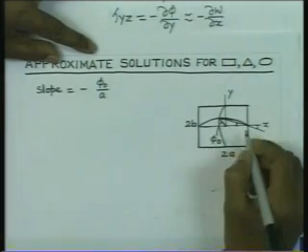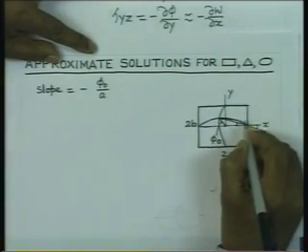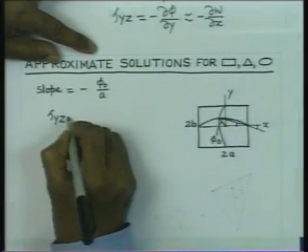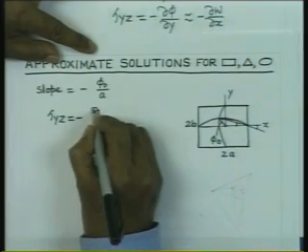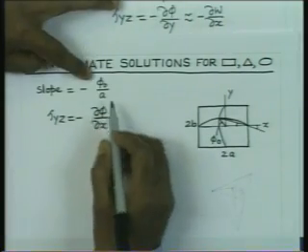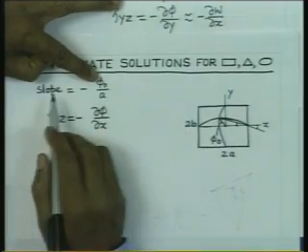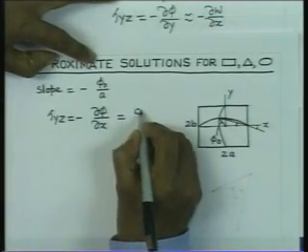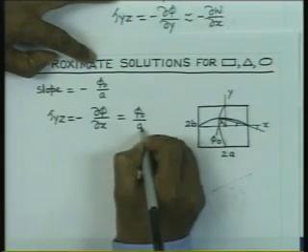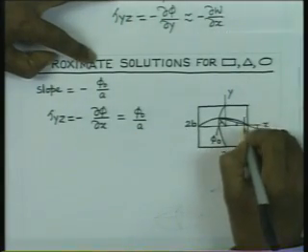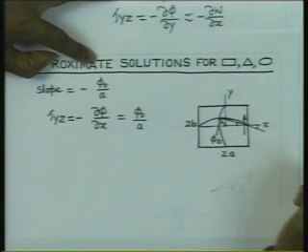And now we know that the shear stress which is going to act parallel to the boundary, which is nothing but tau yz, is equal to minus delta phi delta x, and we get that delta phi delta x is nothing but this slope, and therefore, it is equal to phi 0 by a. So, this is the value of the stress which is going to act parallel to the boundary.